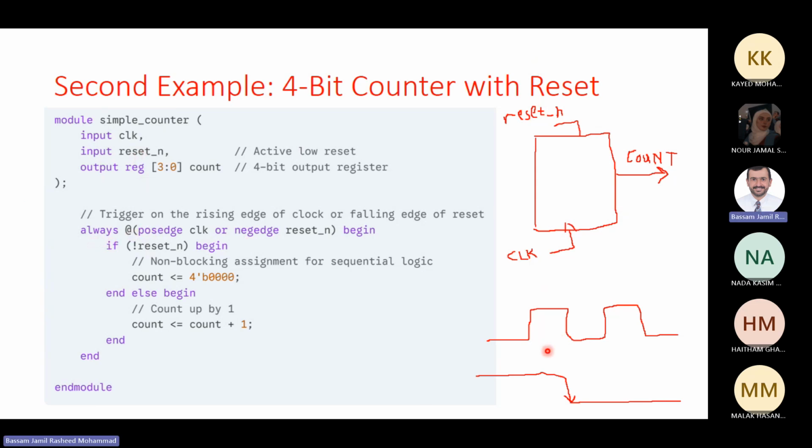Now I entered the block. Suppose, for example, I got reset low here. So when the reset goes low, immediately I will get into this block. What do I need? I check, because either there is a reset or there is no reset. If reset, inverting the reset signal means this is now true, then I assign count 4-bit 0000. What does this statement mean? It means I want to assign to the variable count, which happens to be my output, this value 0. Why do I repeat it four times? Because it is 4 bits. All the bits of the count variable will get zeros, which means the 4 flip-flops inside will now be set to 0, because I received a reset that goes from high to low.